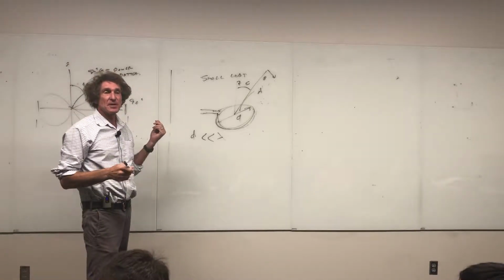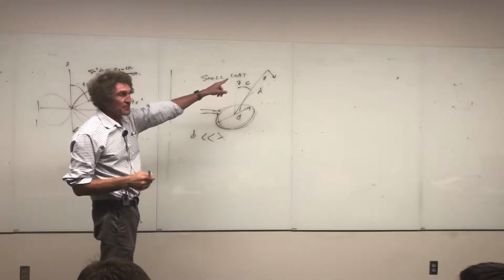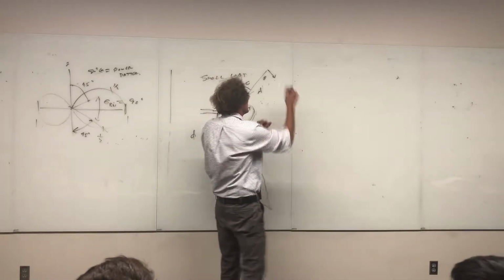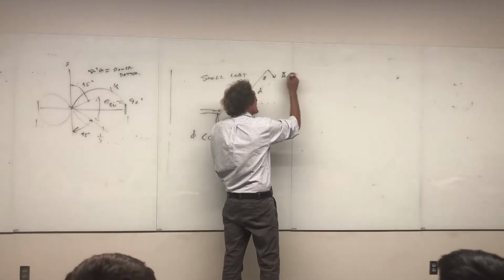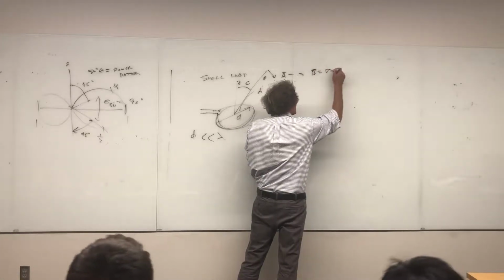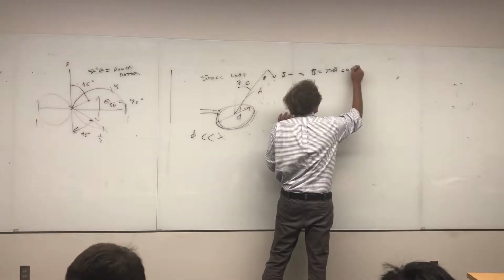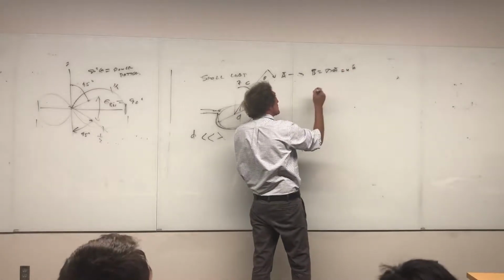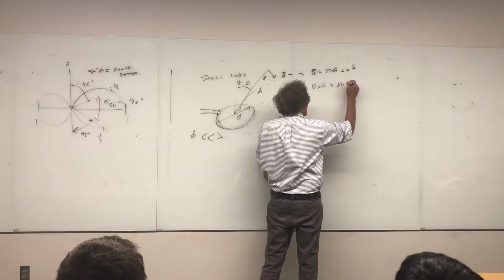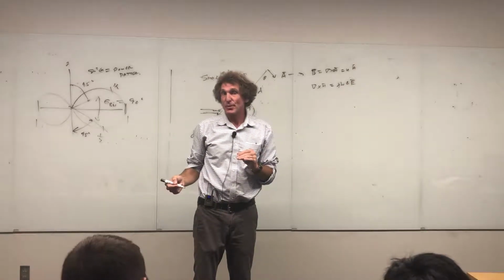The elliptical function integration takes a while to do, but the nice thing is it's a closed form solution to get the fields. You get A. Once you have A, remember what happens. I'm just going to tell you this. Maybe I will do this next time. If you get A, the next thing I do is get B, right? B is equal to the curl of A, and that's equal to mu H. And then I can get the curl of H, and that would be j omega epsilon times E. Therefore, I can get E. Follow me? That's how you would do it normally.